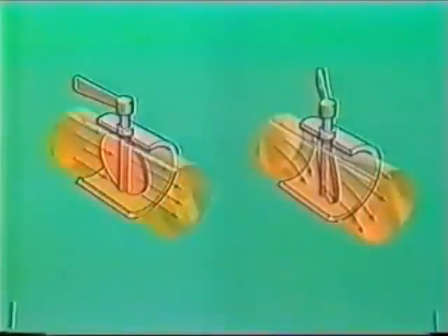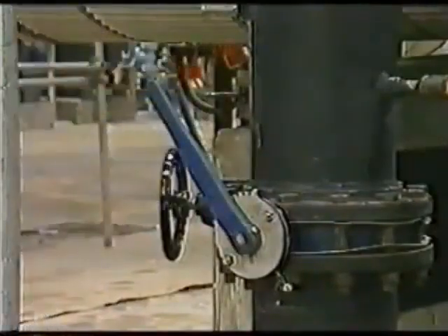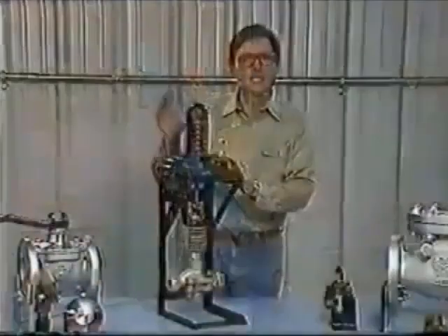Because dynamic forces develop across throttling butterfly valves, they should always be latched into the throttling position to prevent them from slamming open or closed. Nearly all the throttling capability occurs in the first 30 degrees of rotation, so be aware that there may still be a lot of flow through a butterfly valve that is only 1 or 2 notches open.